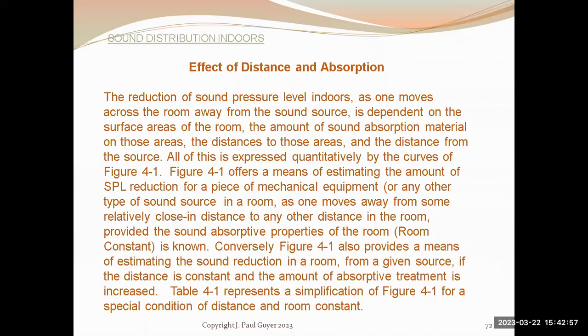And in general, the finished materials, the walls, the ceiling, carpets on the floor, they reduce the sound by essentially the vibrating air molecules impinging on, say, fibers in the carpets or in the wall coverings, and those fibers deflect microscopically and absorb a certain amount of energy from the air molecules.